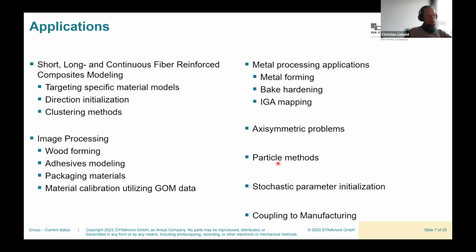There are some particle methods which we support. So, of course, in DYNA, you can basically do a fully coupled particle and structural analysis. Nevertheless, sometimes people just do a particle or a fluid simulation without a direct coupling to the structural, but they can create a pressure output for these particles or for these elements, and then they want to follow up with a structural analysis. So we have some capabilities to transfer the resulting pressures as load segments into DYNA meshes.